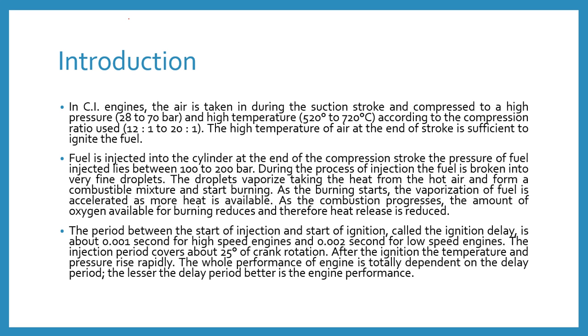But in the case of the diesel engine, pure air is drawn into the engine cylinder from the atmosphere during the suction stroke and compressed. The temperature of the compressed air varies from 500 degrees Celsius to 600 degrees Celsius.